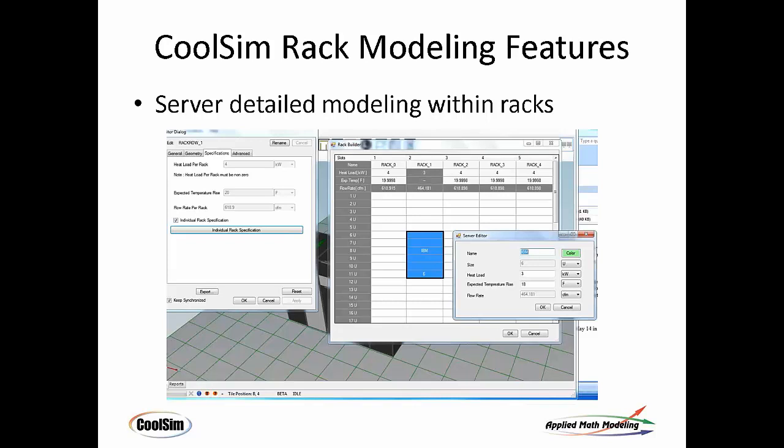You can get it from, oftentimes there are measurement devices near the rack that you can get the loads from, or you can measure them using a current clamp on the circuits if you have to. But that's the detail within the rack.